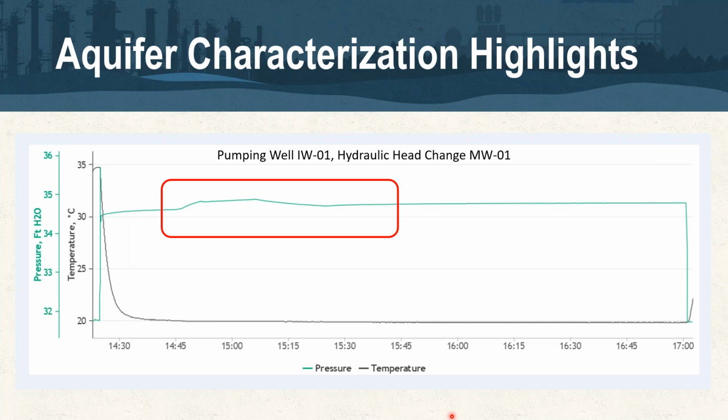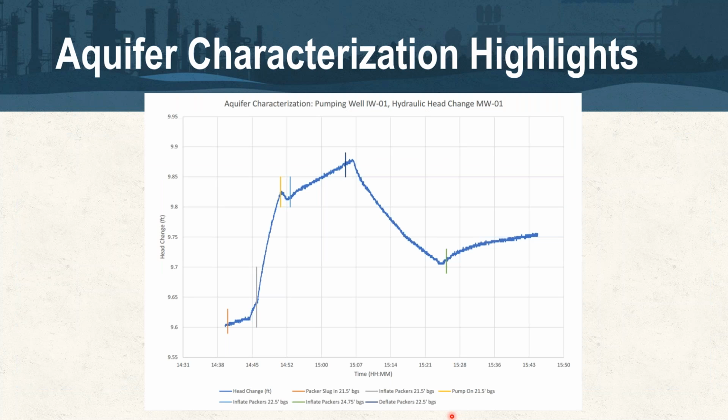So with a click forward, we can look at our other data from the time of performing actions on the site, and then see with a little more resolution and investigation here of looking at these individual changes with the plot. What we see here is actually that while in this particular case, monitoring well 1 did not particularly respond with the pumping test itself to a significant degree, what it did show was that the water within MW1 behaved very similar to what you would see with a falling head test on a standard slug test.